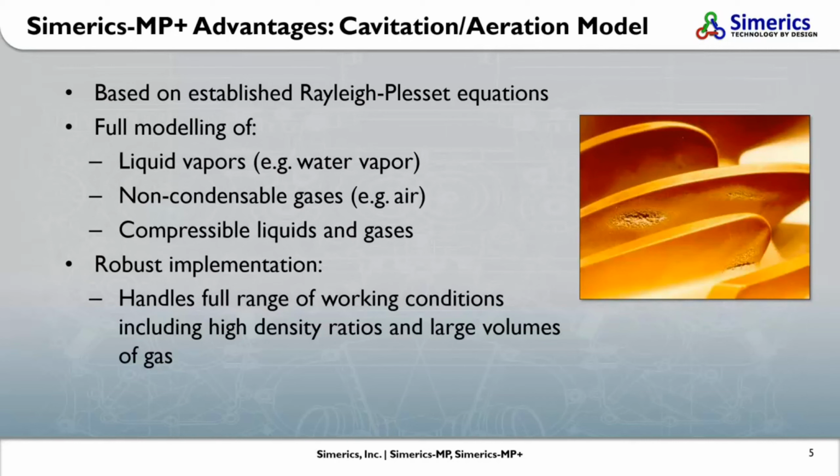Another advantage of Simerics MP+ is its advanced cavitation model. This model is based on the well-established Rayleigh-Plesset equations, which were derived from vapor bubble dynamics. Simerics further expands the original model to include free and dissolved non-condensable gases, such as air.